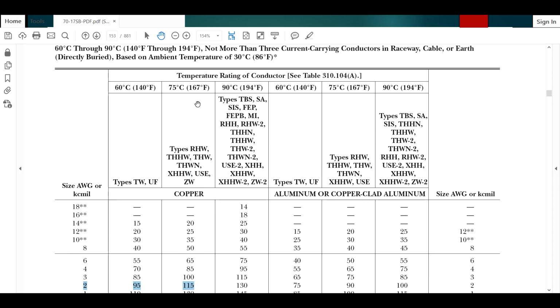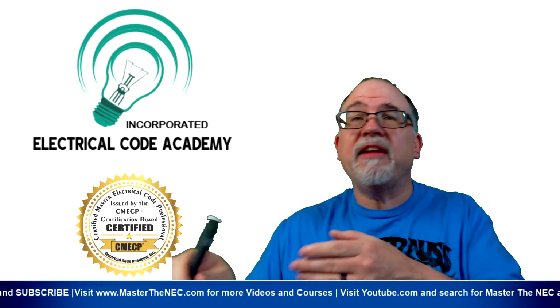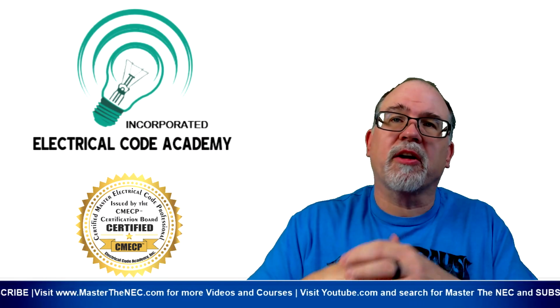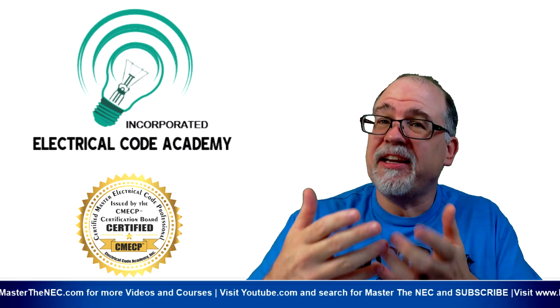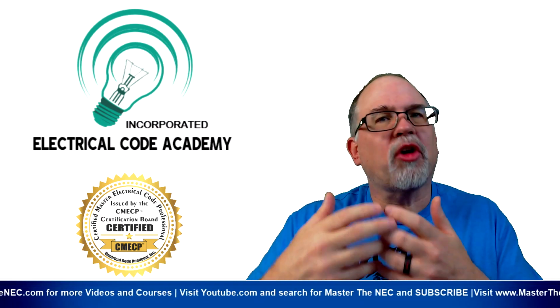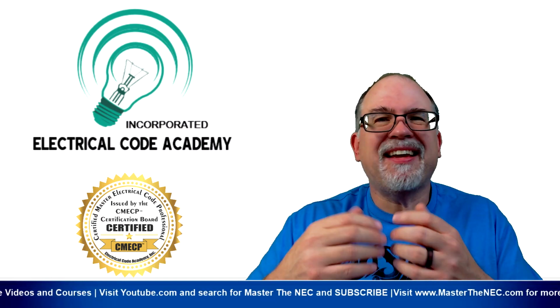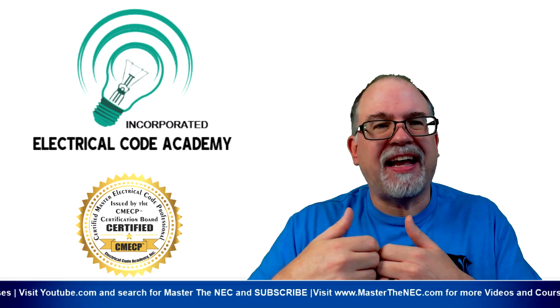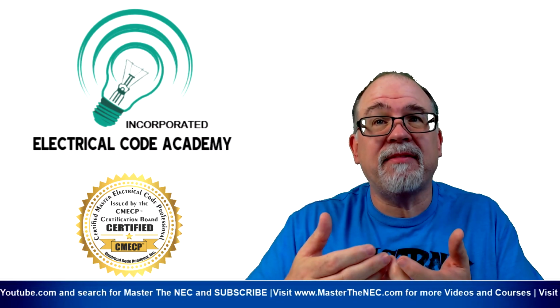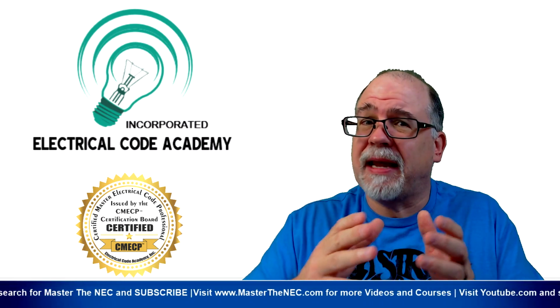Also, we're in the 75 degree column, and I didn't tell you that, so I should probably clarify. The reason we're in the 75 degree column, let's say our conductors are THHN, THWN-2. Now, that's a 90 degree rated insulation. But due to terminal limitations based on 110.14(C), because I have terminals that are rated at 75, and because it's less than 100 amperes, I typically would be in the 60 degree ampacity column.